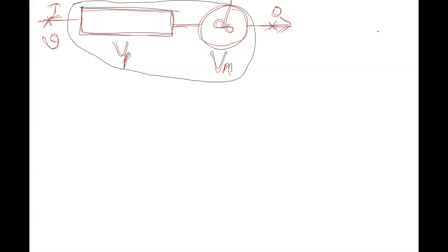So I got multiple answers. Somebody's answer is that it will resemble the graph of CSTR, only that the graph will not start from time t equal to 0. Correct. But at what time will it start? It will be like an impulse response. The RTD shifts by the PFR residence time, right? Vertical and then exponential, a line parallel to time, then decreasing. Not correct. I think identical to the CSTR RTD. Identical, but does it start from time t equal to 0 is my question.